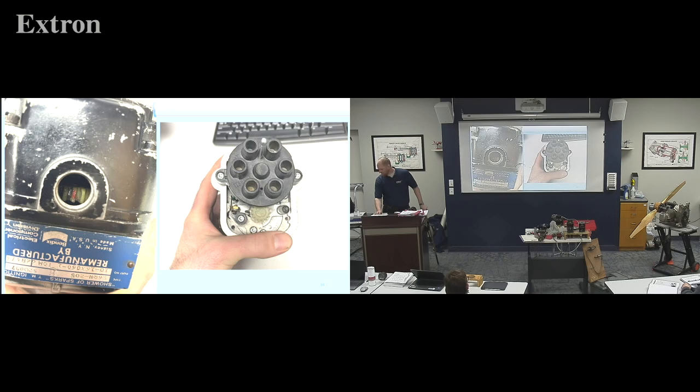Alright, this is a slight review of one that you already saw. On the Bendix mags, which I brought in, they look like these two. A little different brand, and they have a cam that's got switch or contact points that you can look in and see there. We're going to have to adjust those on the Bendix.